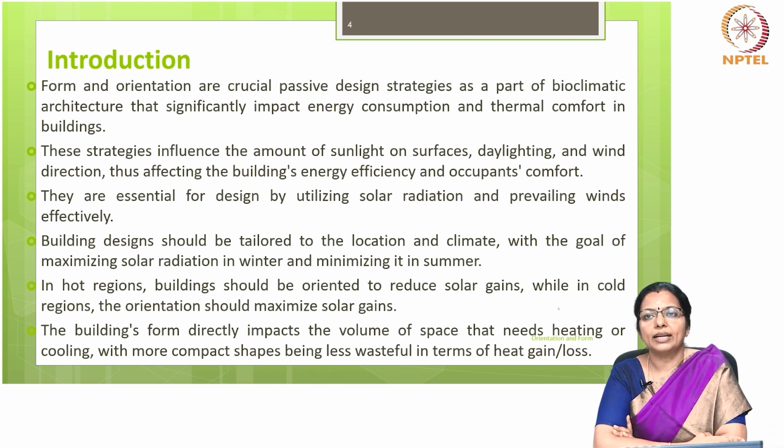The form of a building influences the volume of space that requires heating or cooling, with more compact shapes being more efficient in minimizing heat gain or loss, because if they are compact and placed close to each other, self-shading helps in minimizing the heat gain inside the building.